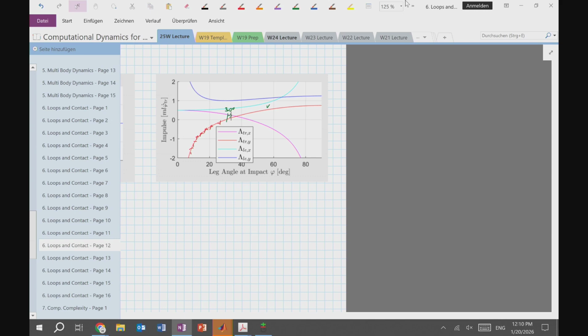And that's really, still for me, hard to stomach, right? But it's a consequence of the modeling assumption where we say everything is rigid. If you would look at this as a soft system where everything is deformable, then you would, of course, get rid of these discontinuities, and you would see that there are unique solutions. But they are, I don't want to say unstable, but they depend heavily on the initial conditions. How do I choose my initial condition? If I'm penetrating a bit more, then I will stay in contact. If I penetrate a little bit less, I will leave the ground.